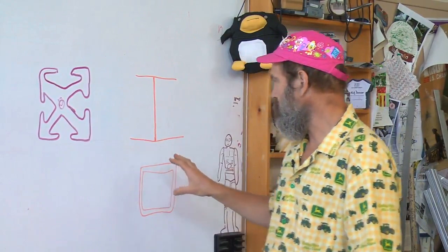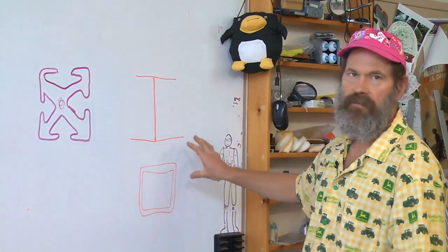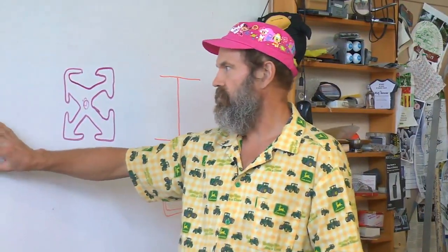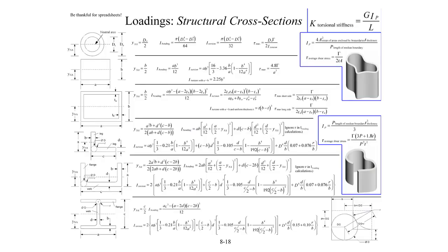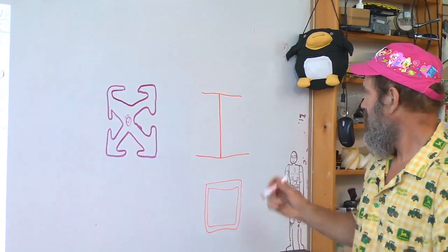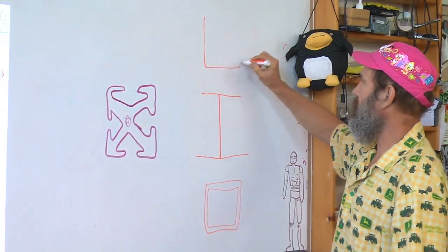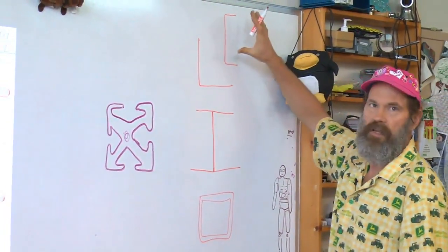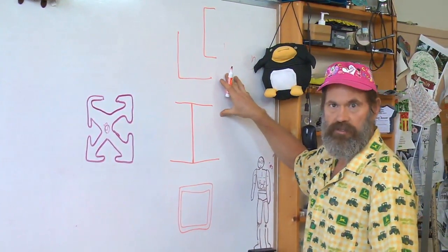Now, the torsional stiffness of these open sections can be very easily determined, even for some more complex ones, by these simple formulas, or the more complex exact forms for some common shapes are given. But any of these open sections, while they're very useful in bending, remember they're basically useless in torsion.